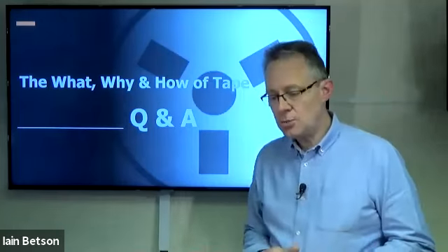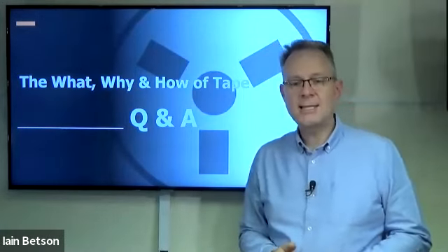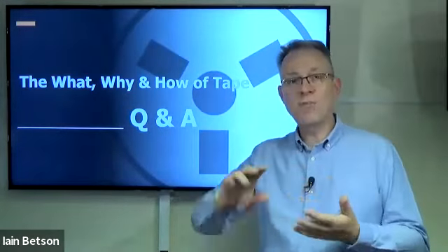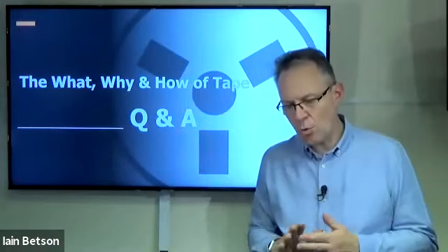How does it compare to new tapes and old tapes? Quite frankly, if the tape can mechanically stand up to it, a tape can take as many passes as it wants. Yes, as you play it, it will suffer some oxide wear. Oxide will be worn off. That's why we have to clean tape heads. But if your tape's not suffering from sticky shed, you saw those pictures where the heads were completely gummed up by the sticky shed, then frankly a tape, whether it's new or old, will take many passes. I won't say infinite. It will eventually start to wear out.